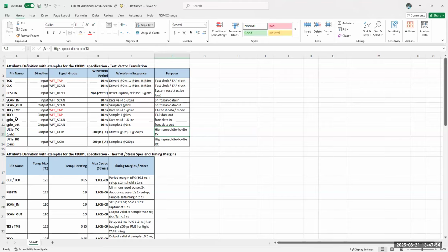Okay, yeah. You can treat this like, for example, the SDC constraint, where they have input delay and output delay of some magnitude, and that magnitude is with respect to the reference clock of so-and-so clock pin, right? It is something like that for the translation tool when they want to cyclize this pattern and force some values and sample some values from the inputs and outputs.